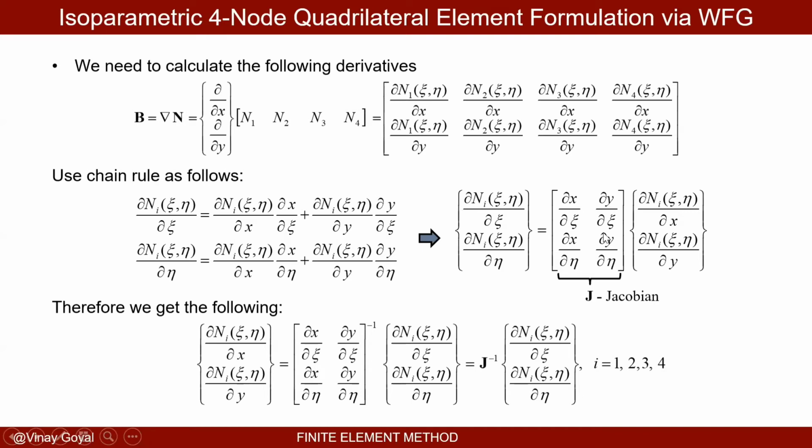So we're ready now. We can invert J, which we call the Jacobian. No need to worry. This is the information that contains the geometry. This is the only thing that tells you how the quadrilateral got mapped into that square. This contains all the information. And these are all numbers, by the way. Every element will have these matrices filled with numbers, right?